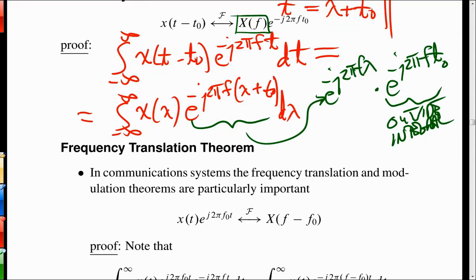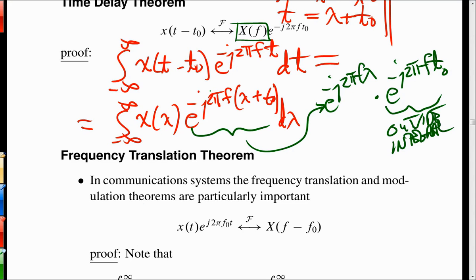And then the dual of it, which we'll start off with next week, is complex sinusoid and frequency shifting, or frequency translation. We'll also look at duality again too, which tells you that this has to be true, because the Fourier transform pair being so symmetrical means you can look at this idea of duality. Time shifting gives you a complex phase. Frequency shifting gives you a complex sinusoid. I mean, there's a dual relationship. This I'll have to go to next week, but you see a similarity between that and that, right?